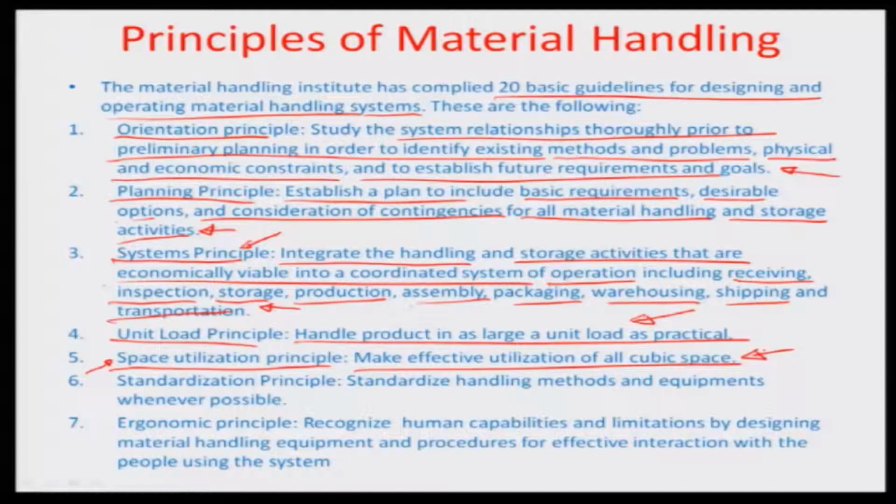Wherever possible for storage applications, introduce vertical spaces. Wherever there is a question of fitment or assembly, you have to lay out the material horizontally. So moving from vertical into horizontal has to be done, and a three-dimensional map has to be prepared, which can be of optimum distribution.